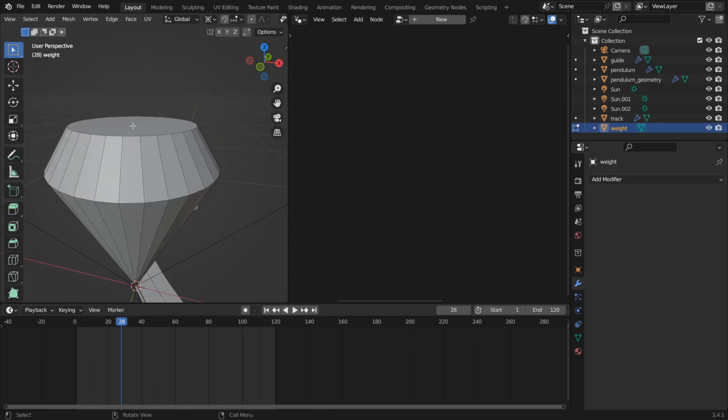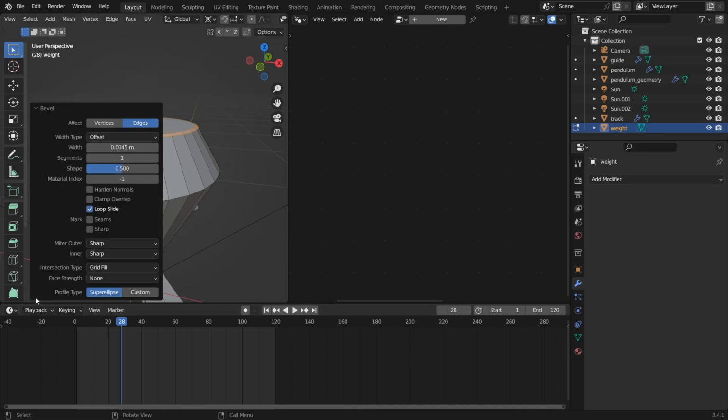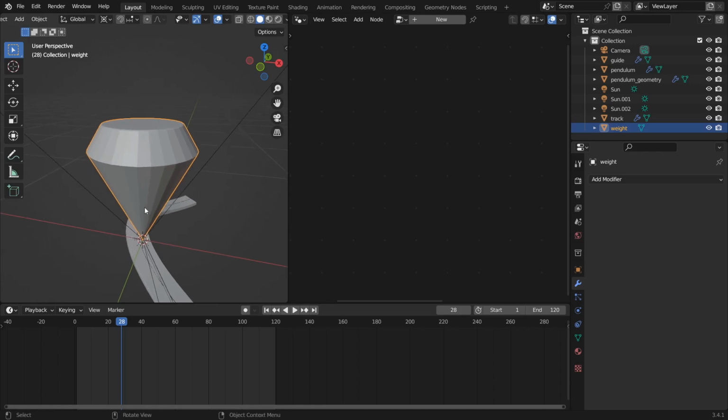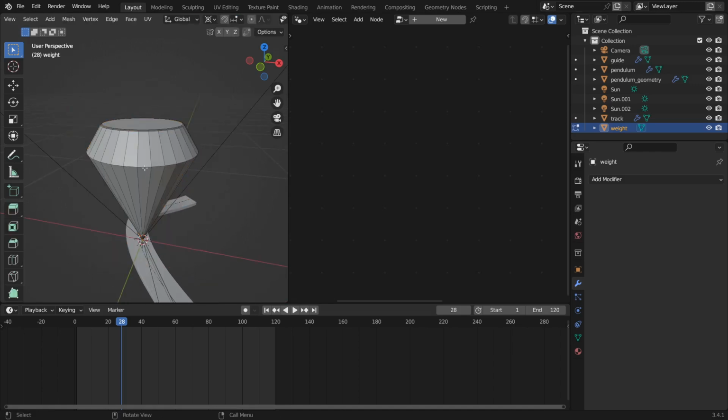And then I'll select the new top face, and I'll bevel that to get a nice edge. And I'll click into the bevel operator pop up, and up the segments to something like 6 is probably good. I'll do the same for this edge loop going around the edge. So what I'll have to do is switch to edge select mode by hitting 2 on the keyboard.